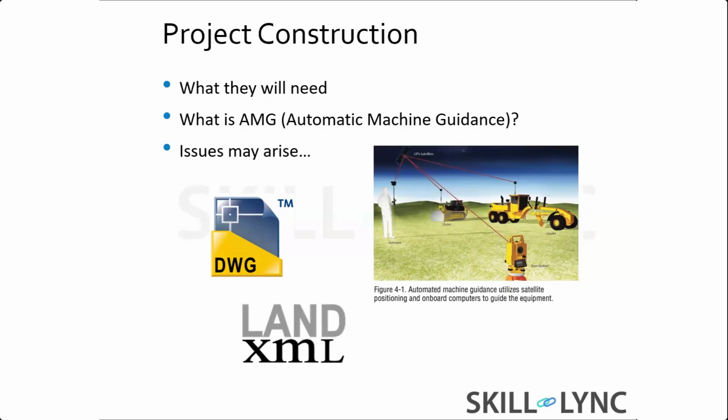So what the contractor will usually require, they want DWG files usually. Okay, that's Autodesk. Bentley is another software company that does this. They're very popular in the roadway agencies. However, in the end, the contractor is the one who is doing it, and they may have a license of Bentley, but typically they have AutoCAD and they want DWG. And their graders will allow them to bring in what's called a DXF file, which is a different exchange format, but it's DWG based. So that's why they want that.